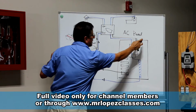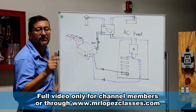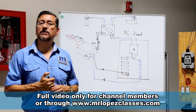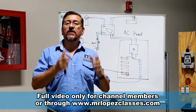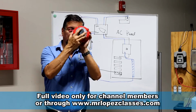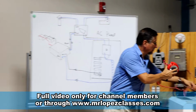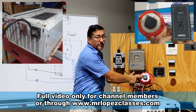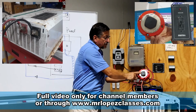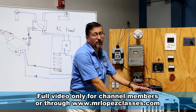Normally in a typical boat, on the AC panel you find one breaker with the label inverter slash charger. Some people say this is the breaker in order to activate the inverter. No. Remember, the inverter is activated from the switch selector that supplies the DC power. This is the breaker or switch selector used to activate the inverter. The switch selector is located here in order to interrupt the positive at the input of the inverter. That's the input. In some cases you install, instead of the switch selector, one breaker, to activate the input of the inverter.